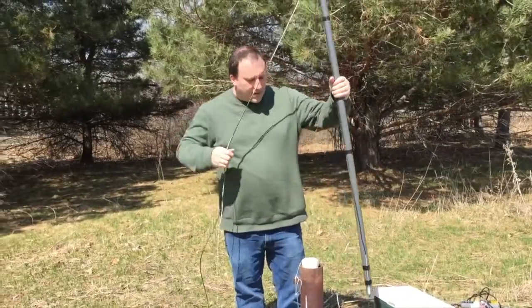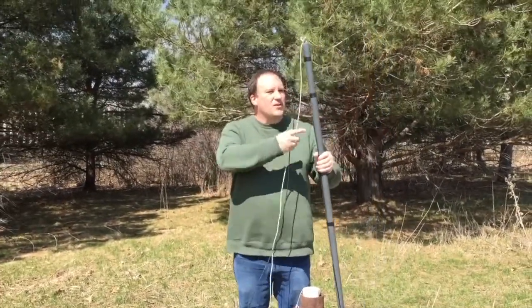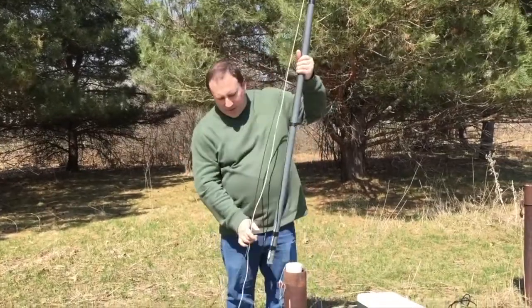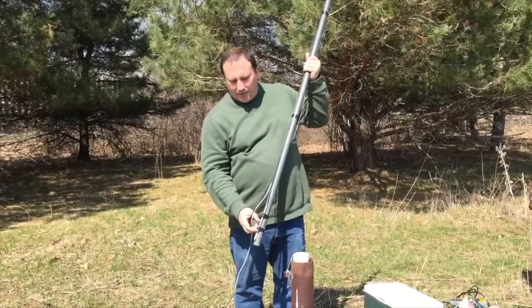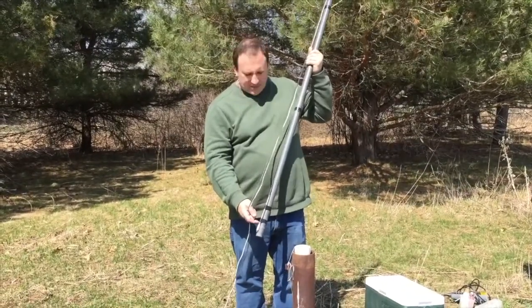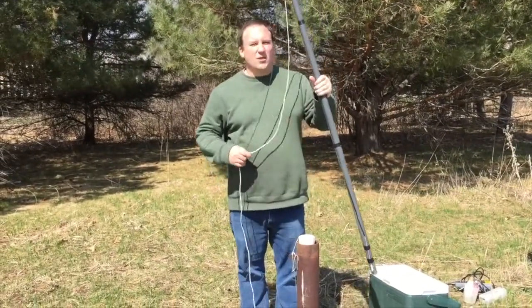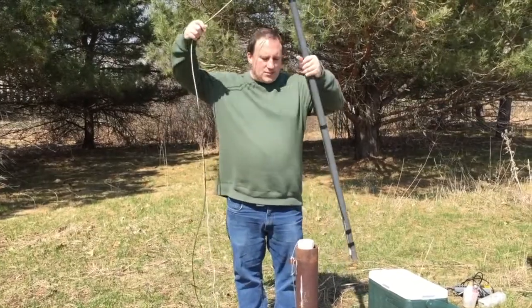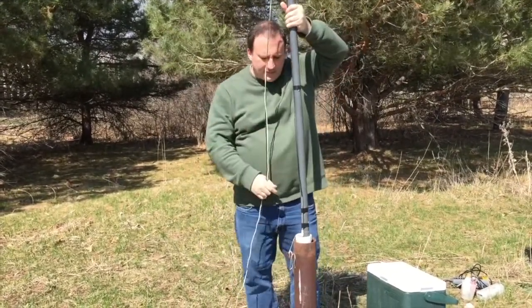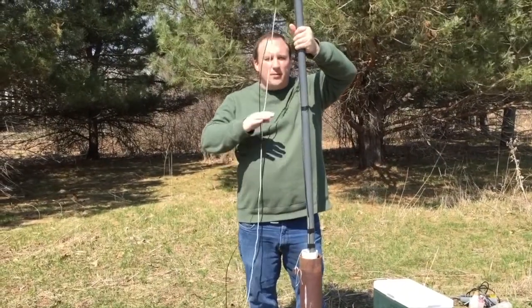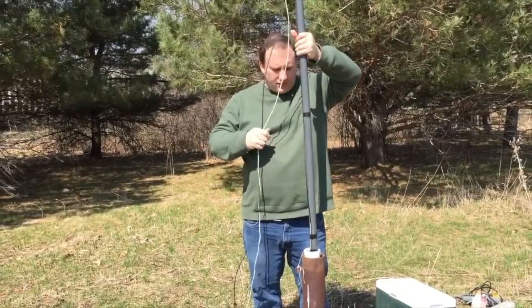All right, so here's our slug. Our water level indicator's on here. It's sort of a way we can measure the depth. Because there's a couple inches of distance here between the bottom of the slug and where the water would be located when it beeps, let's say that's 2 inches. So I'm going to be around 11 feet. That's where I want to have this thing hanging before it goes in the well. I've waited a sufficient length of time that the water level has probably recovered to its original value.